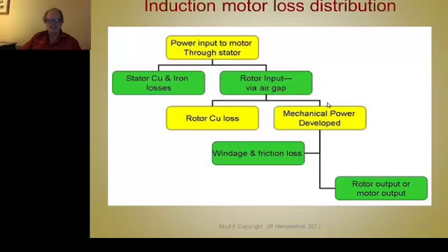The permanent magnet machine, depending on its design, can have eddy current losses in the magnets and even in the core, and certainly in the retainment sleeve if it's used to hold the magnets onto the OD of the rotor. But since there are no windings, there are certainly no ohmic losses or copper losses.